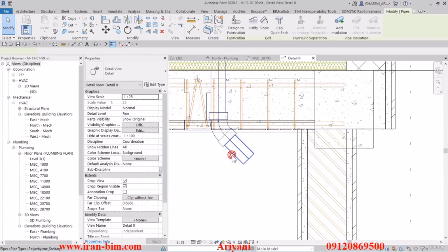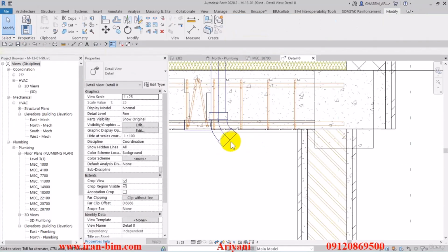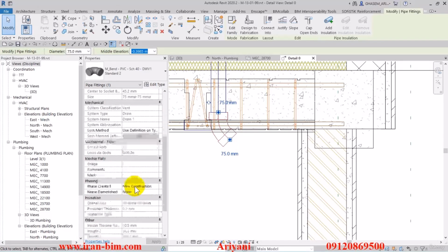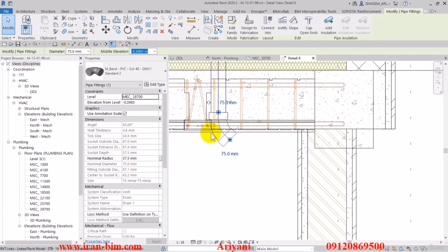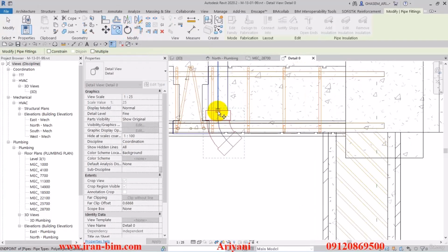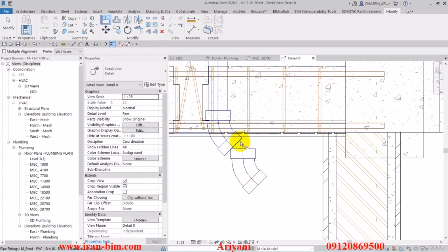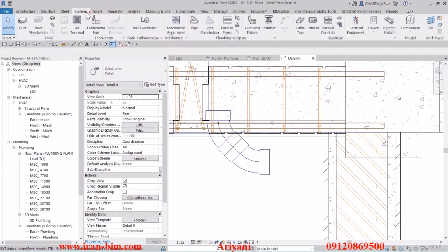Then I'll delete the extra added parts, then select the newly drawn part, and we can see in the dimension settings the angle is actually 45 degrees. Now I can select the pipe piece itself, then copy it and paste it here next to it. Alright, then I'll move it right over here and then lock it to the rest of the piping like this.